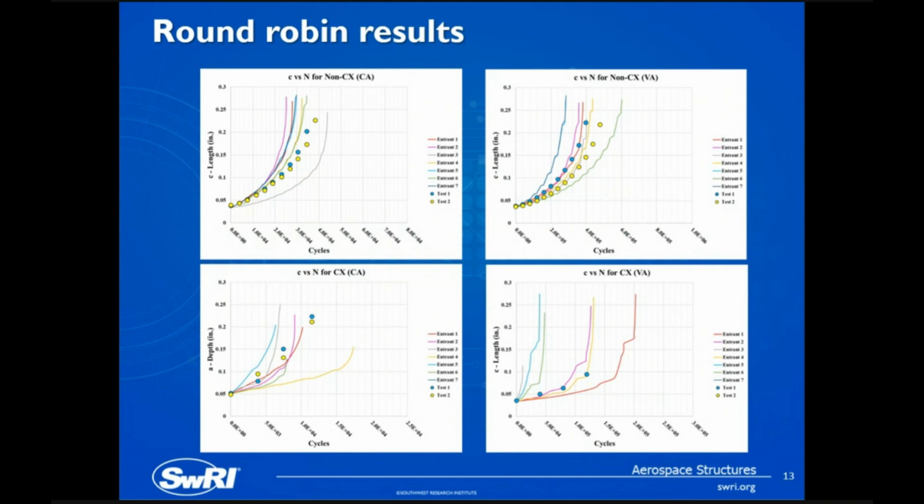We've got the red and the pink. They're both pretty accurate and pretty conservative. There's really very little variability in all the different analyses. This is kind of a verification of a fairly simple problem. Then we add the complication of variable amplitude loading. You see a little more variability in the different analyses. We add more complication with the residual stresses, more variability, and then finally the residual stresses and the variable amplitude loading, and you see the most variability, which makes sense.